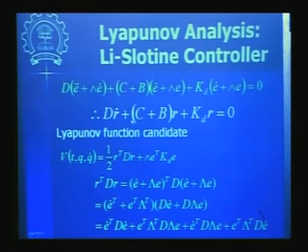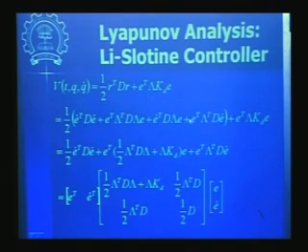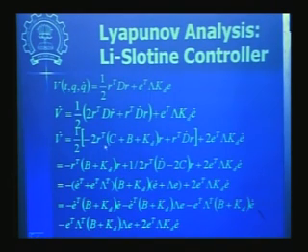This is just the negative of C plus B plus Kd times r. So I have substituted that in this equation: 2 times r transpose (C plus B plus Kd times r) for D r dot, with a negative sign over here, and other terms are as they are. Now you can see that this D dot minus 2C can be separated out.